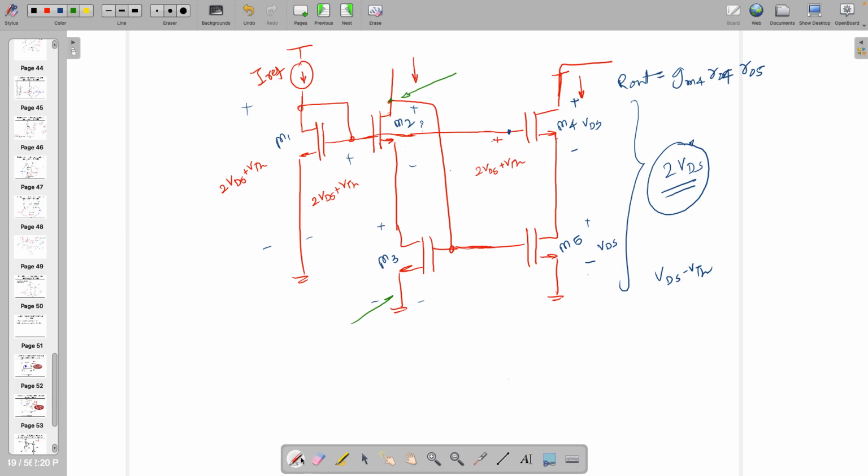Just go ahead and tell me how much voltage is required to make sure that both the transistors are in saturation. Look, the minimum required voltage is actually VDS. I'm referring to VDS set as VDS, by the way, which is 250 millivolt or more than that. Aman, are you following? So, tell me, what is the voltage? Am I going fast or going fine? There is no unique answer, by the way. One of the answers I'll show you, but that's not the unique answer. As I told you, the minimum voltage required is VDS. You keep that.